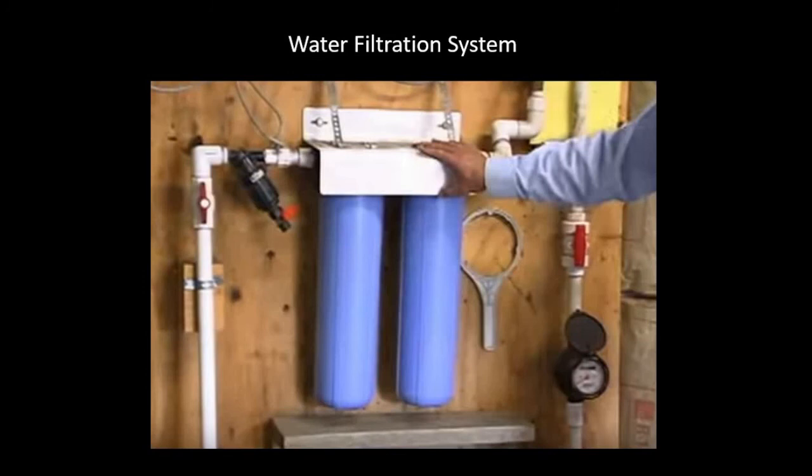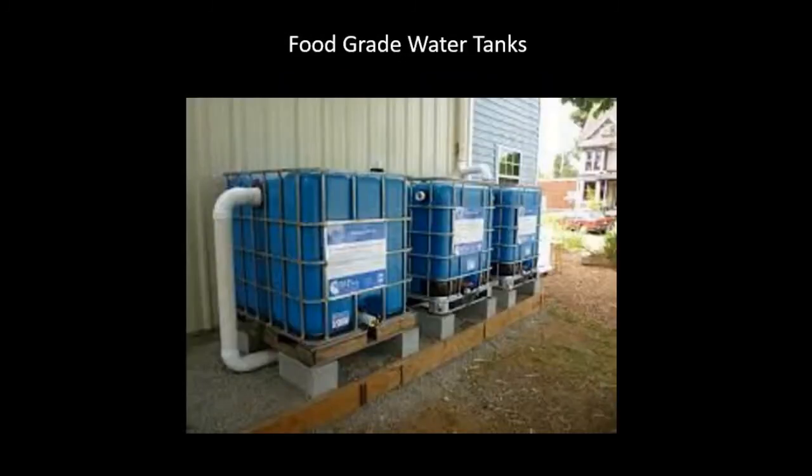so that when it comes out the other end, you don't have any particulates at all. And one other thing that you could add that I don't believe he has, but it would probably be a good idea, is a UV unit. And what this does is then the blue filters here take out any particulates that would float in the water, and then the UV kills any bugs, any microorganisms. So you don't have anything in there to contaminate your drinking water.